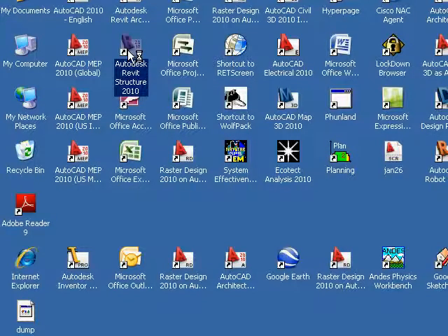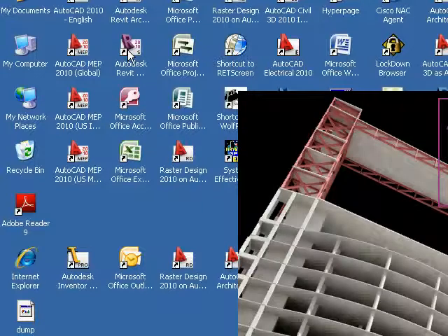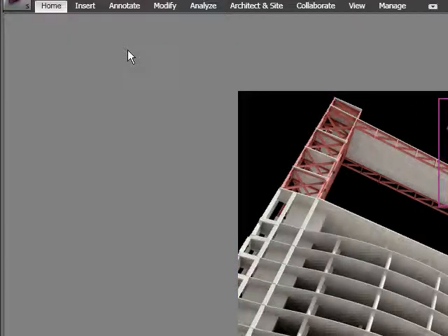I'll begin a new project and I will then import. Remembering the coordinate system in Inventor is important. Layering in Inventor doesn't seem to be there. You can also push out from Inventor into DWG. You're going to see that's DWG and DXF. It has historically been one of the basic ones that you go through as a middle ground. One link you remember we had issues with was going from AutoCAD DWG 3D objects into Inventor. We'll see whether that process works; it looks like the links are there. It could be some setting stuff.